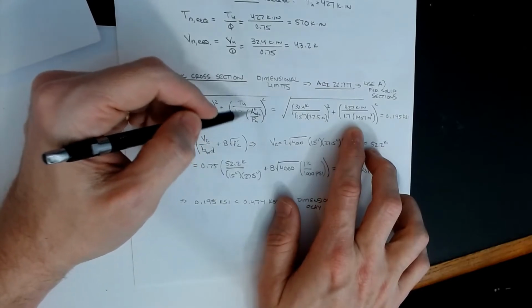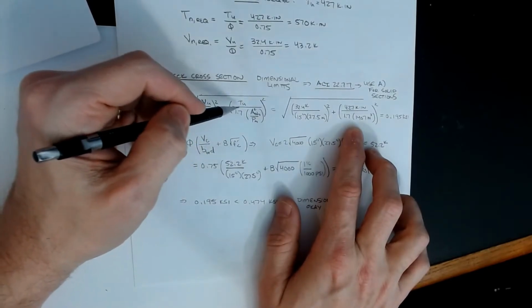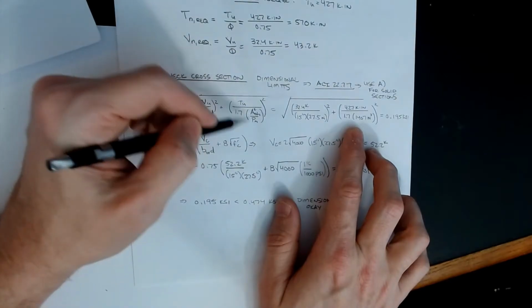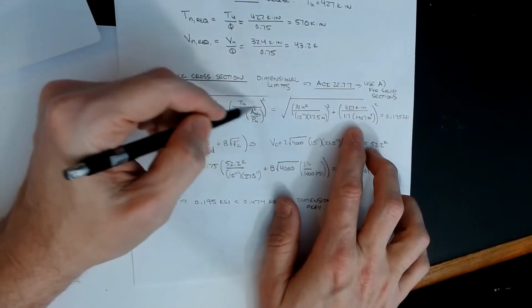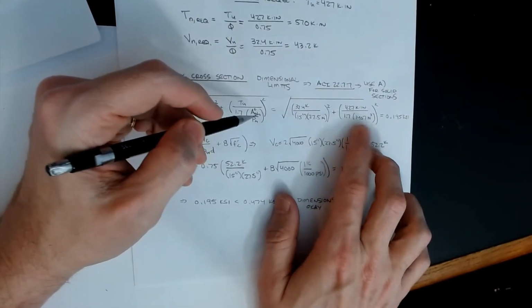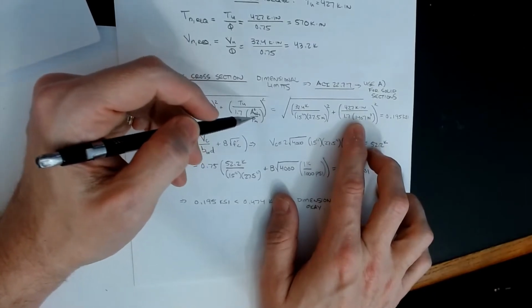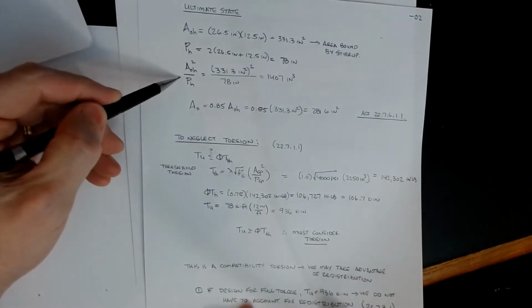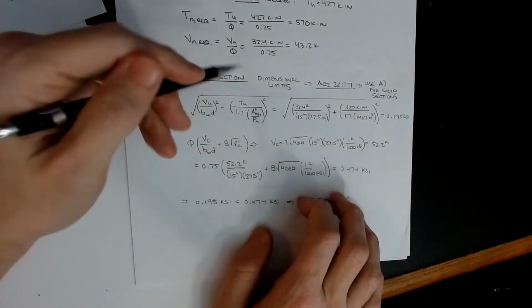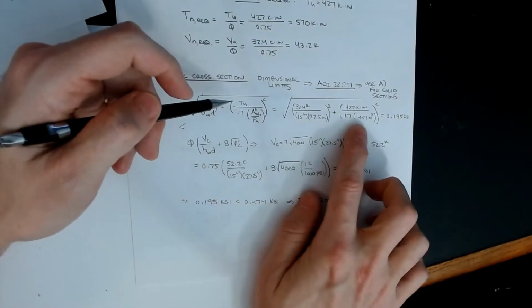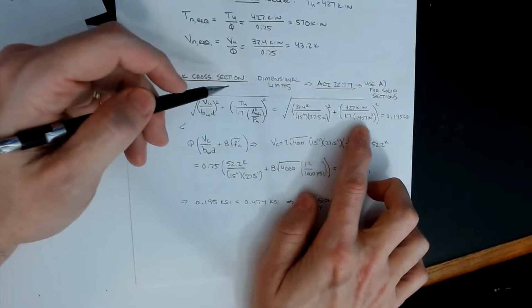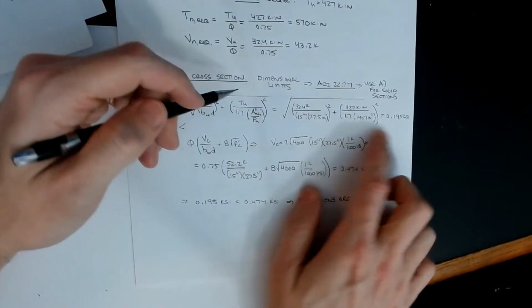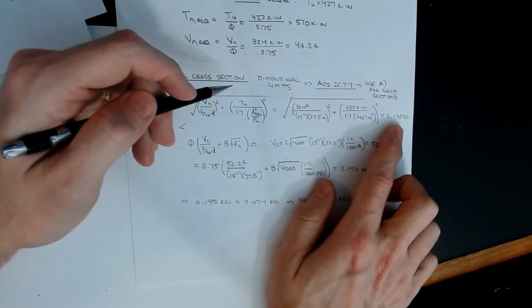Now notice this formula is written a little bit different. In the original version of it, pH was in the top, it wasn't in the bottom. But if I refactor it this way, I've now got that quantity calculated from the ultimate section properties when we did it. And we found that number was 1407. If you remember, that was this guy right here. So we restructured the formula a little bit, but it's the same formula. If I do the math on all this, you'll find that the total stress from the applied loads is 0.195 KSI.